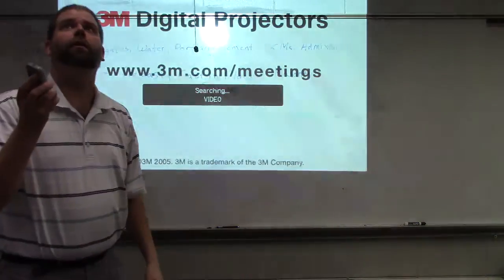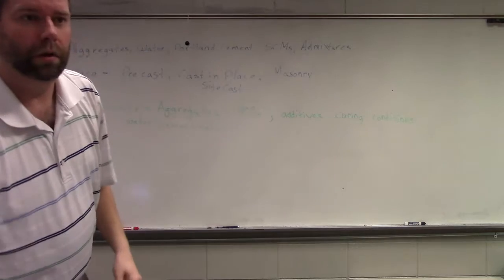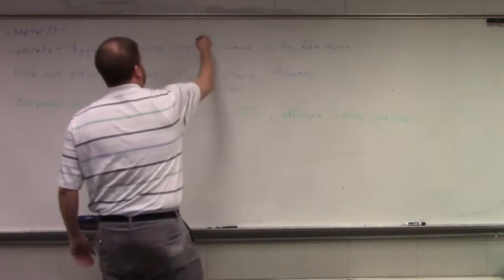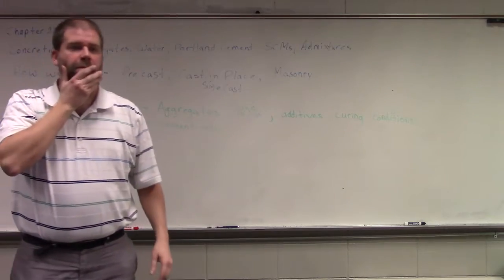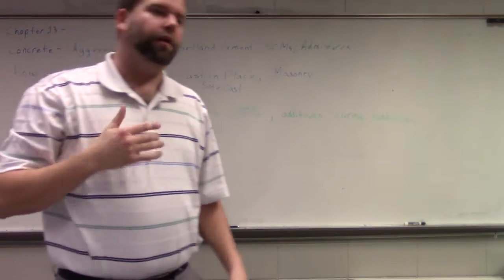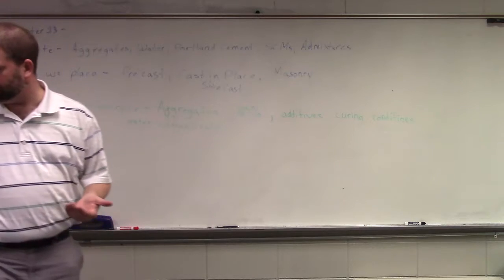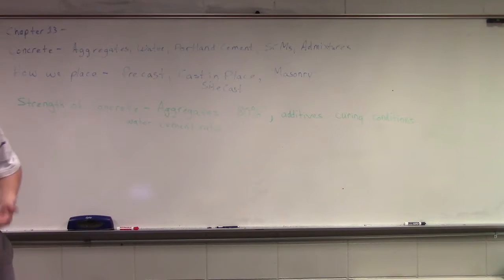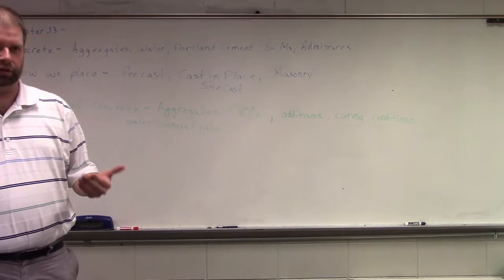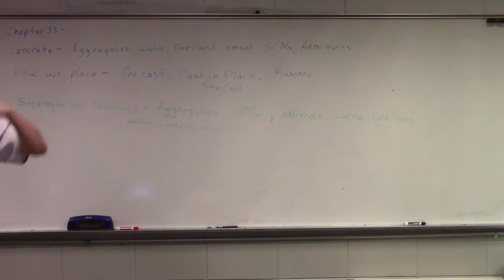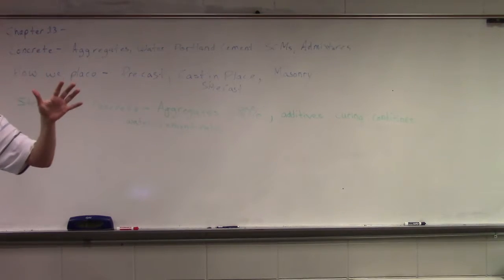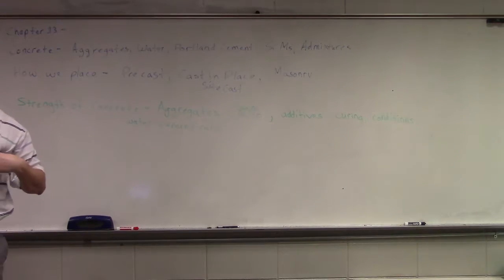This is because every time we did something more structural, it seemed like we were using the big ready mix bags with the bigger aggregate. Yep. You have to remember, there is an ASTM standard, a specification for aggregates to be used in concrete construction. Okay. And regardless of if you're using it for patio construction, foundations and columns for a structure, or a massive structure, those aggregates still have to meet those requirements, okay?